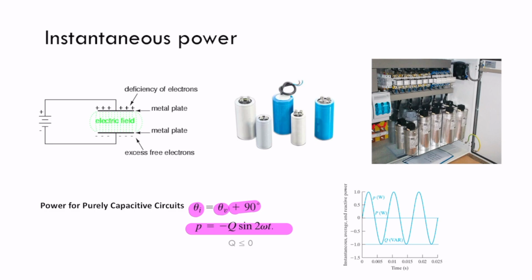When the current signal is positive or negative, it's charging, and the other part will be discharged, right? So the instantaneous power is oscillating between some positive value and negative value, but on average it's zero. Again, a capacitor, if ideal, is not consuming any energy.